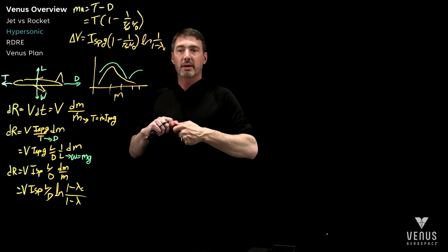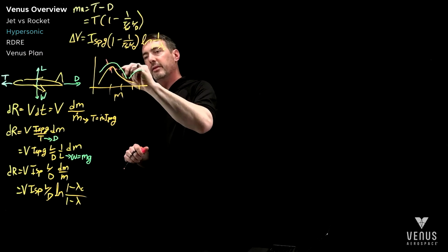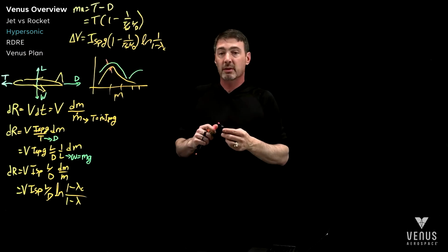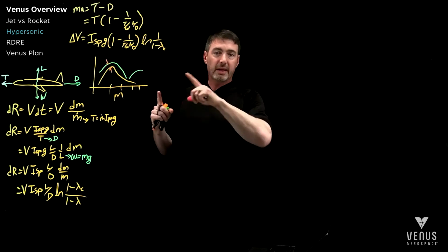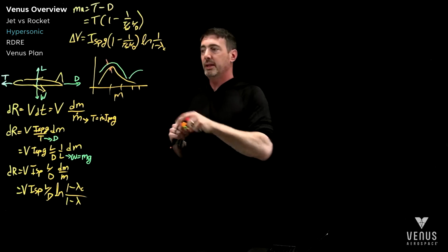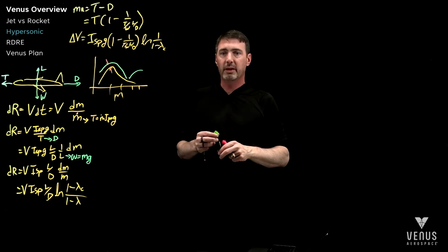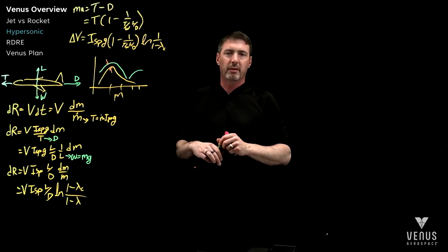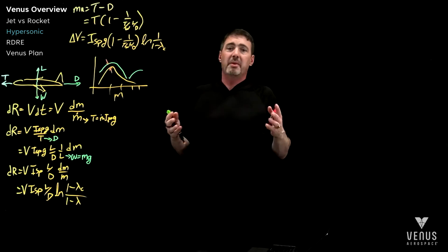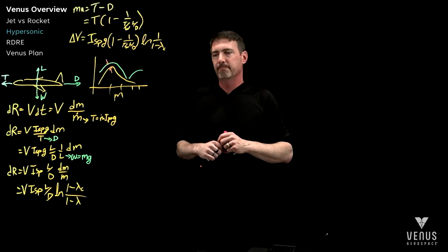And so this penalty term, even though we integrated it here and pretended like it was constant, it's not constant. So really you have to go back up to this term and integrate your way forward. But right here, the lift of the aircraft compared to the drag is pretty brutal. This is why, if you look at a military aircraft, the standard thrust to weight might be something like 1, just to make sure you can get through the sonic barrier.